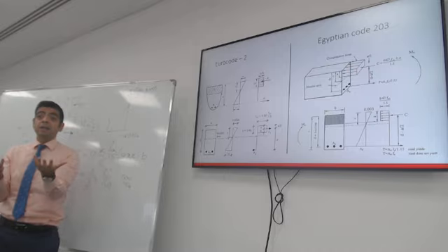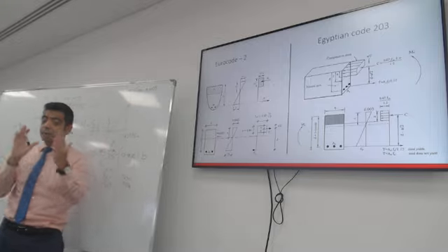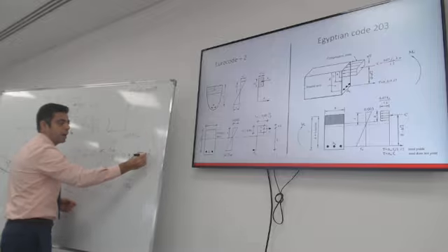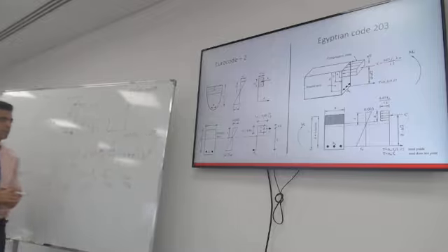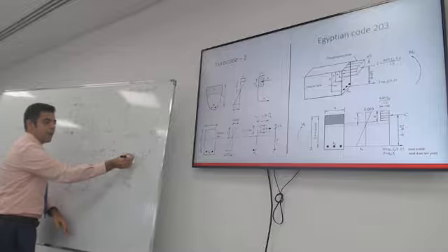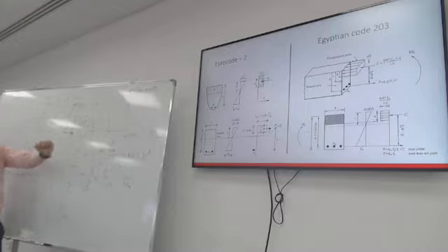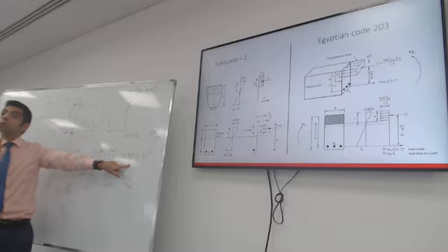I can accommodate their design and build my beam to be 200 millimeter wide, and use this as an initial assumption. When you look closely, the only thing missing is the actual distance of the neutral axis. That'll be a very important number to control.